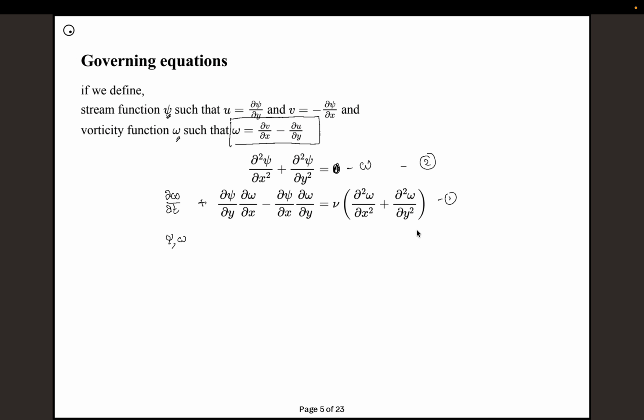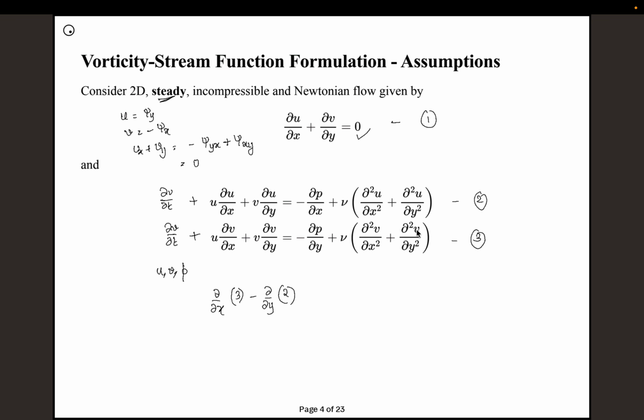Before going to the boundary conditions, let's say you have some other terms in the energy equation also. Let's say you are solving a natural convection problem, then you'll have additional terms here in terms of, say, the Boussinesq approximation, where g is along negative y. Then you'll have one more term that comes up here.